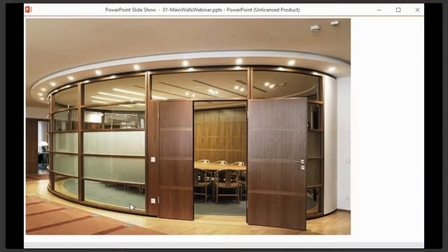Now, the thing about this is, it's basically this sheet is wedged in between the floor and the ceiling. That's it, basically. So it doesn't form part of the structure of the building, and you can take it down. So you can remove this afterwards. You remove the track from the top and the bottom, and you just fill them. There might be a bit of repair work, but this is why it's called a demountable partition, because you can then take them and put them somewhere else, put them in another part of the building.